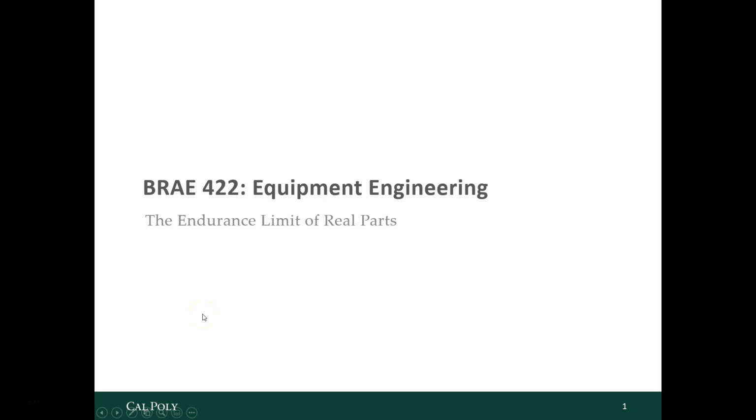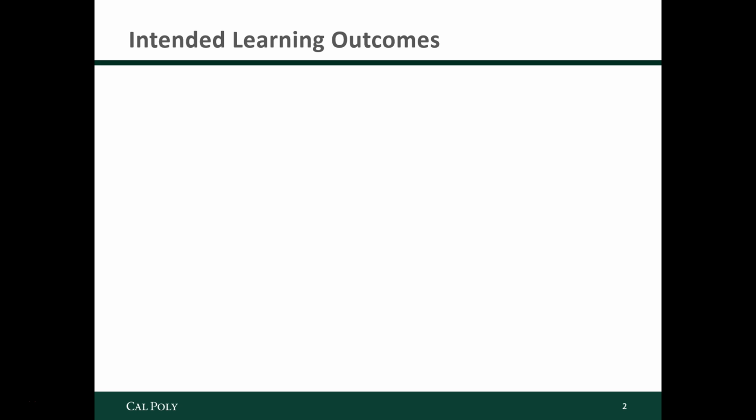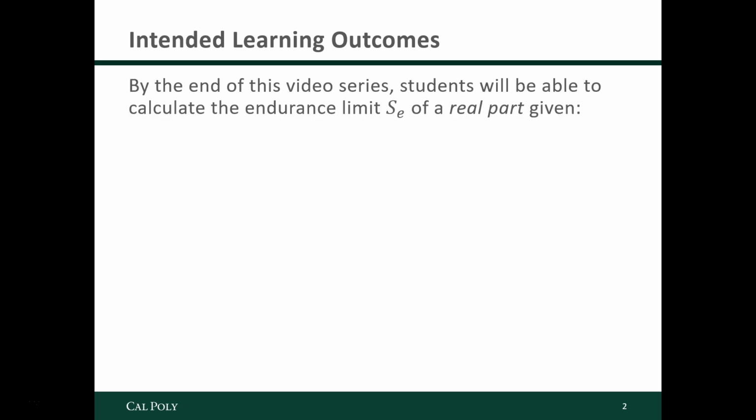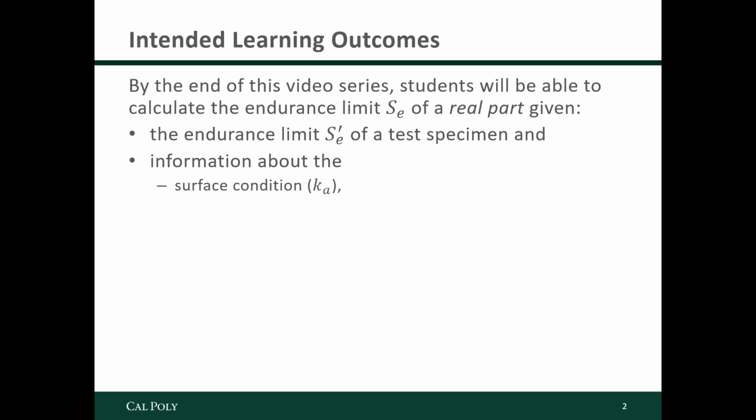Hi class, today's video is about the endurance limit of real parts. So what I want you to get out of this little video series, starting with this video, is you'll be able to calculate the endurance limit S subscript E of a real part given the endurance limit of a test specimen, which we'll also learn to approximate just based on the ultimate tensile strength of the material. Also information about the surface condition of the part.